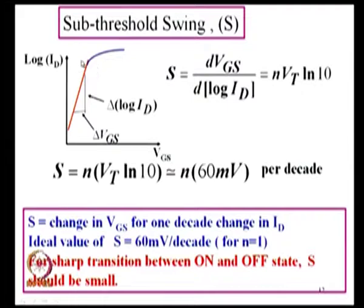When you want to go for low power devices and low voltages, you need to have this threshold voltage as low as possible. Now, if the swing is 60 millivolts per decade, I will give an example to understand this. If n is equal to 1, it is 60 millivolts per decade. What is the meaning of that? The current will reduce by 1 decade when the gate voltage is reduced 60 millivolts below the threshold voltage.